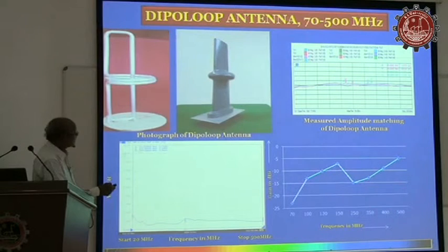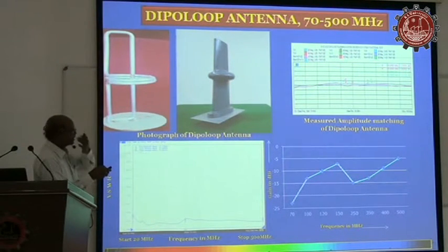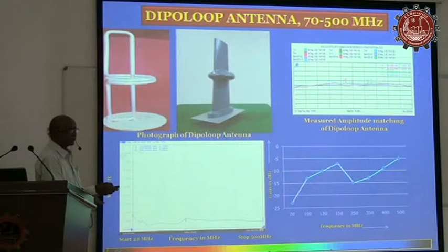This is one antenna we recently developed, one year back. Now the proliferation of radars has come down to low frequency, 70 MHz, to defeat stealth, because most aircraft developers and armed forces are using stealth aircraft or stealth ships. To detect stealth platforms, if you use microwave frequency, you cannot detect them, because they use various shaping techniques to make them stealth. So the radars are now designed even at 50 or 70 MHz.